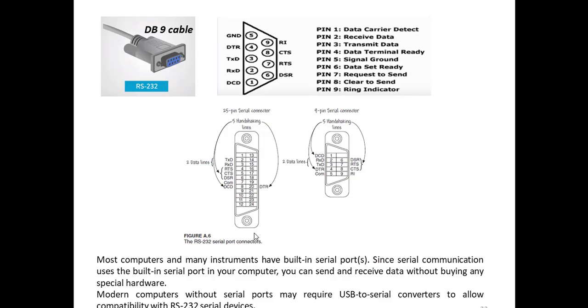RI are there. So for example, for a 9-pin cable, you can see that pin number 1 is the DCD. No matter which cable it is, they are both DCD. So this is like a universal pattern. And for example, pin 6 is DSR. Here pin 6 is DSR, and there pin 6 is DSR. So if you Google DB9 cable map, no matter where you find it, they are all the same.